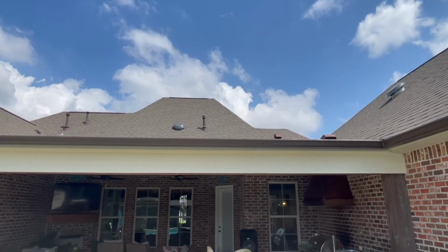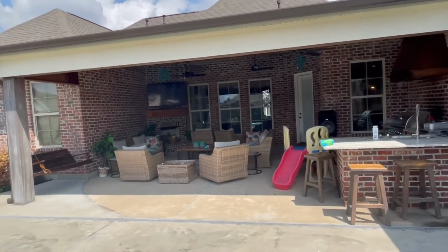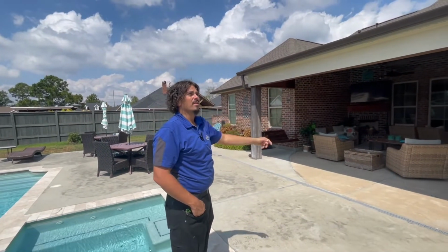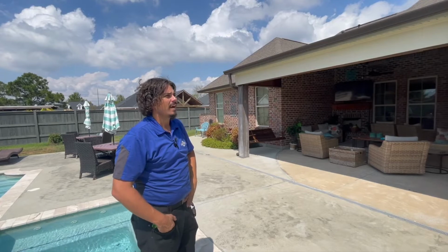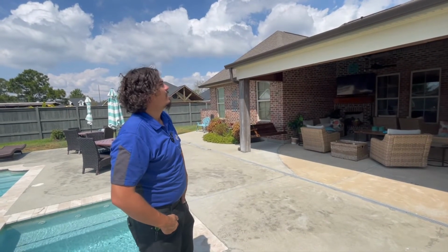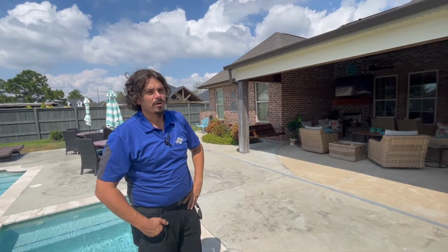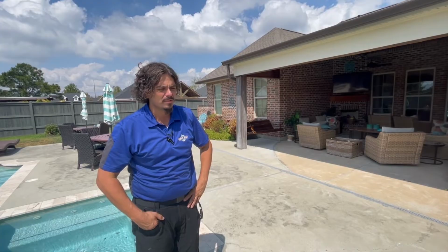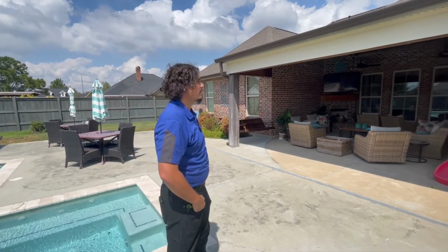It's going to do its best to pull from the soffit, but it could be pulling from the ridge or even the house. Seeing what I'm seeing, I don't like to jump to conclusions, but those could very well be worsening our problem. They might not be what caused the initial problem, but they could be worsening it.